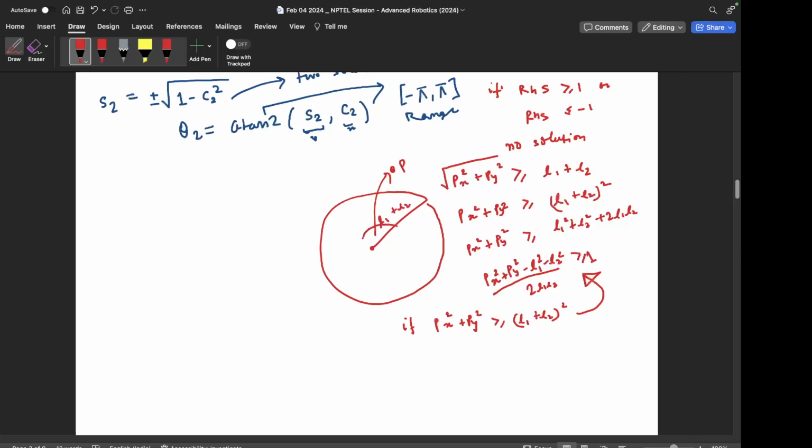And the second case would be for when the links are of different length, that is, the second link is shorter than the first link, so there is a space inside it which it cannot reach. So basically there is an annulus. As you would remember in the previous discussion hour, we drew the workspace of a 2R manipulator when the link lengths are not equal, right? So there is an annulus, and this is the case when the second link is shorter than the first link, right?